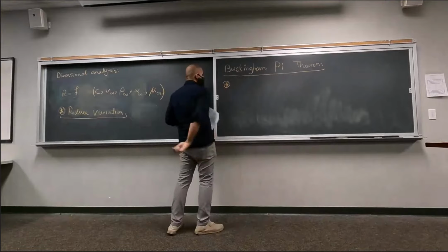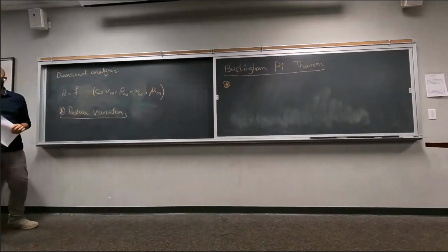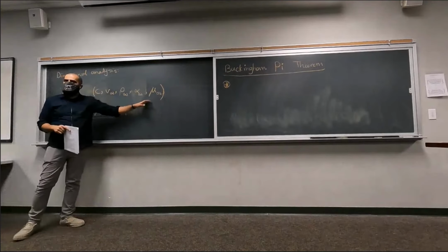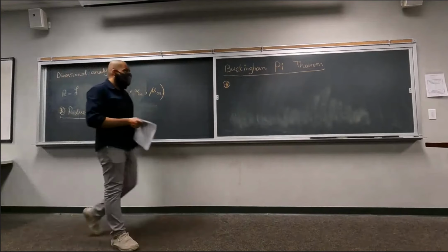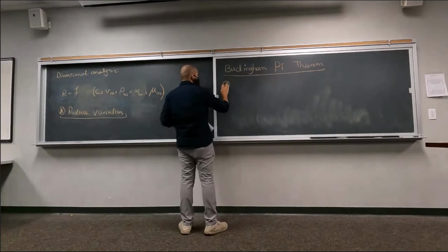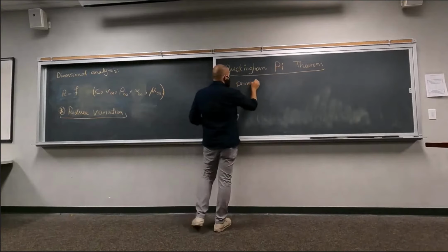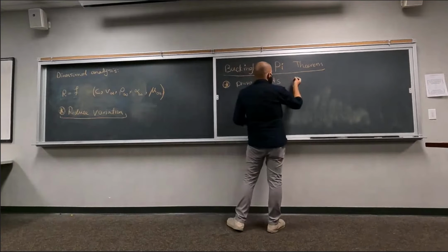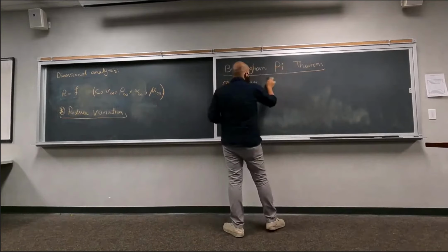Okay, so what should we do here? The first step has to be to determine the number of dimensionless parameters you are going to need to be able to replace these physical quantities, right, with those dimensionless parameters. How can we find those? It's pretty simple. The first thing is you have to find the primary units, or primary dimensions, let's call it dimensions, in your system.